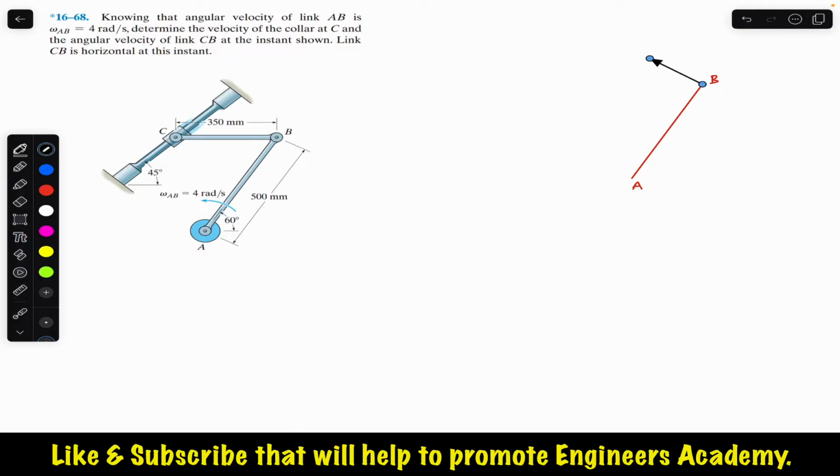So this is that velocity of B. This is making 90 degrees, and it is given here that link AB is making 60 degrees. So we need to represent that 60-degree angle here. If this is 60, and if we draw a horizontal line here, then this angle is 60. So if this is 90 and this is 60, then this is 30. This means that VB is making an angle of 30 with the horizontal.